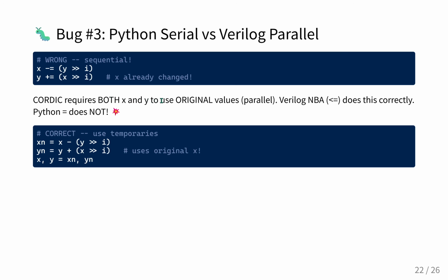It's strictly parallel. And the CORDIC algorithm mathematically requires that the new X and Y be calculated using the original, unupdated values of both. It's like translating an algorithm from Python to hardware isn't just learning a new language. Yeah. It's literally like moving to a universe with different laws of physics, where time happens all at once instead of in a sequence. That's exactly what it is. Yeah. If you use a sequential mindset in hardware design, the math just cannibalizes itself.